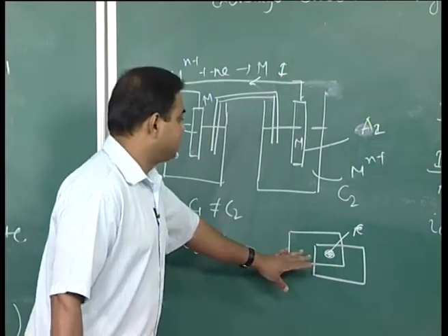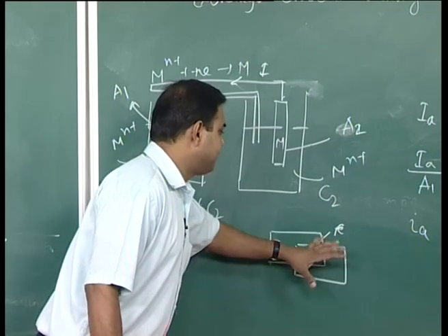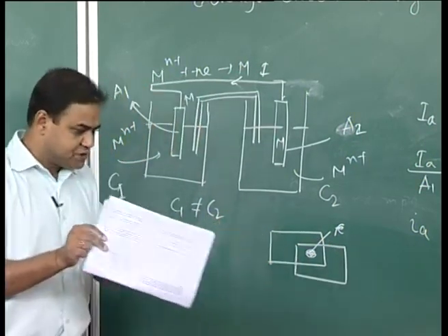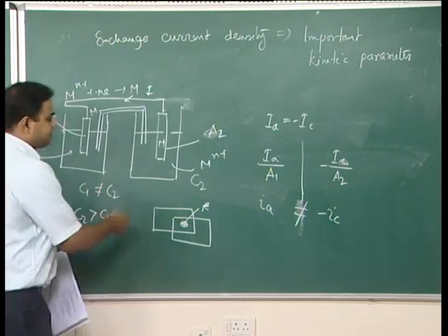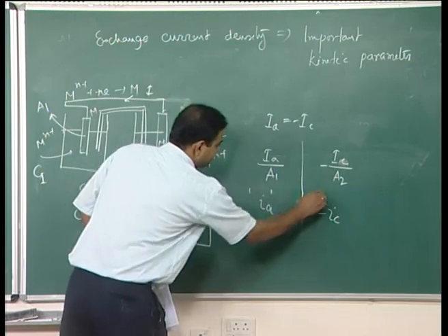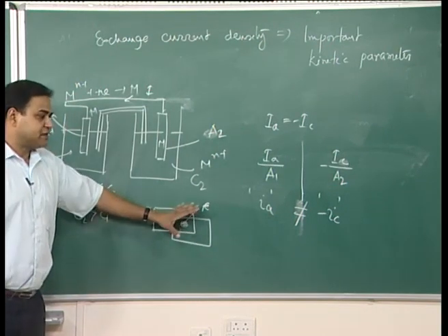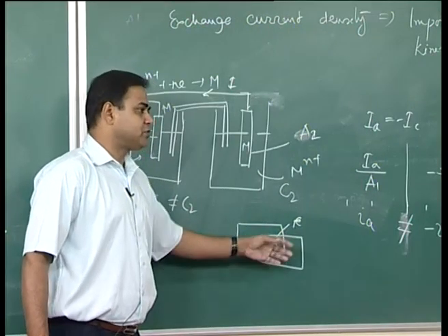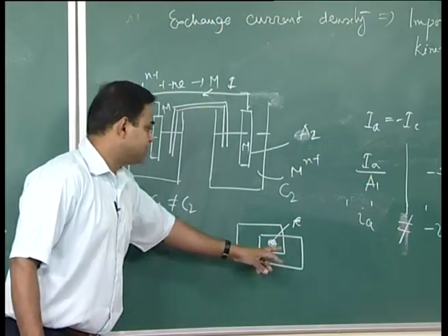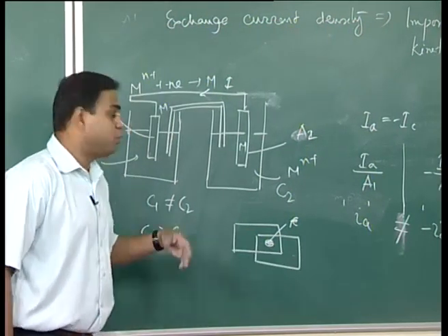So, we were discussing this iron rivet. If an iron rivet is used to fasten two copper plates in a seawater system, this situation becomes very crucial. The current density is what matters, not the current value. It is a closed circuit, so the current in the circuit is the same. The current flowing through the iron rivet and through the copper is the same.